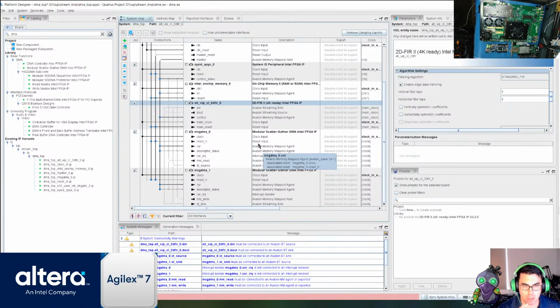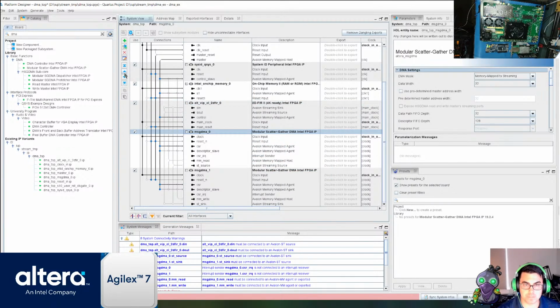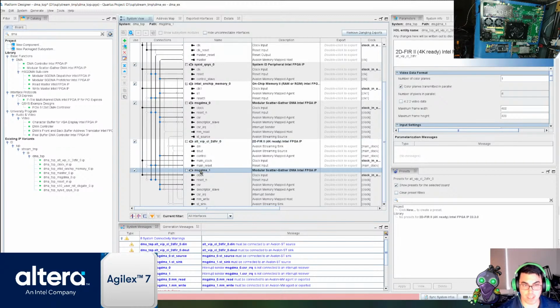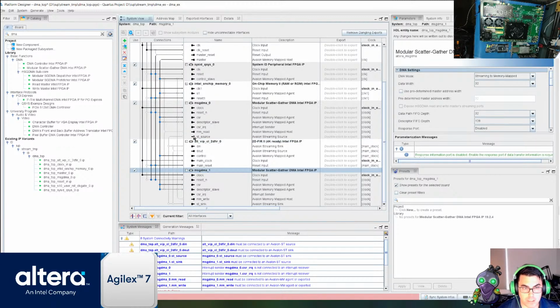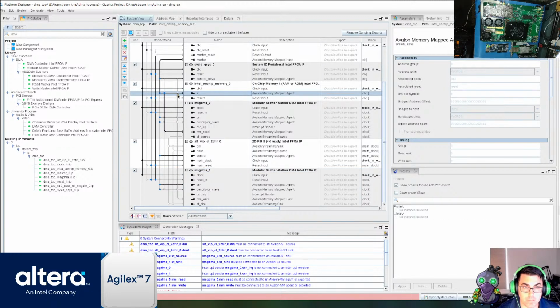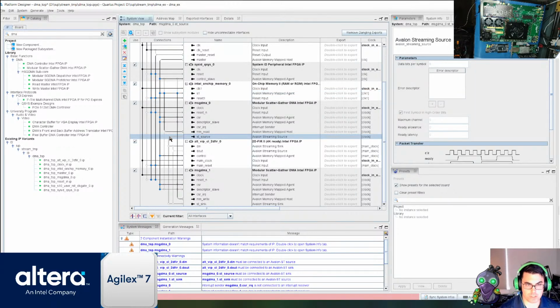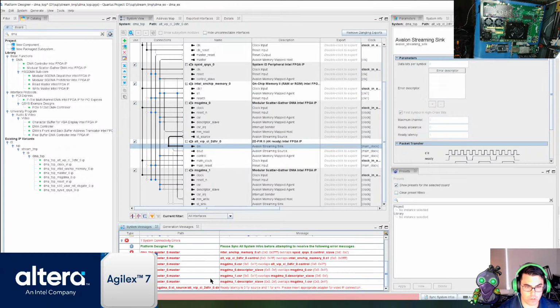Okay, next is a little of the confusing part. So we have DMA out video and DMA in. But if we try to take this source and stick it to the D in here, we're going to get a little error right here where the read latency doesn't match.